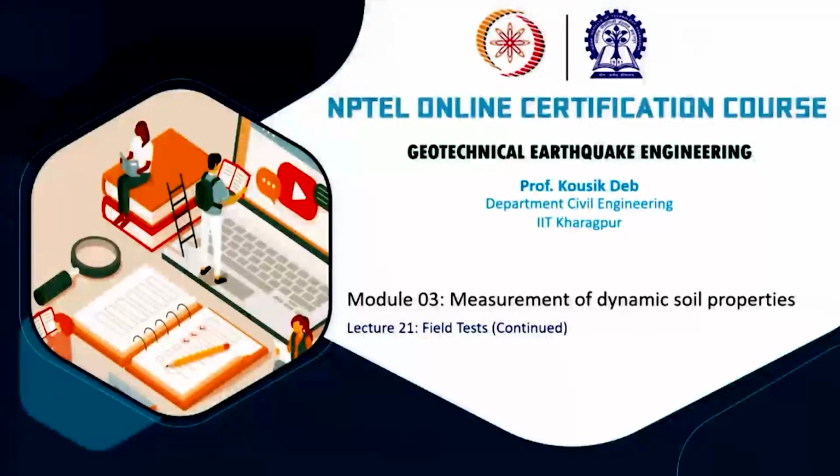So, last class I discussed the seismic refraction test, and I derived the equation for the horizontal layering case, but only for the two layer case. Now, I will discuss the equation for the multiple layer case as well as for the inclined layering case. For the multiple layer case, in the previous class I discussed the two layer case. Now, if I discuss it for the multiple layer case, suppose this is